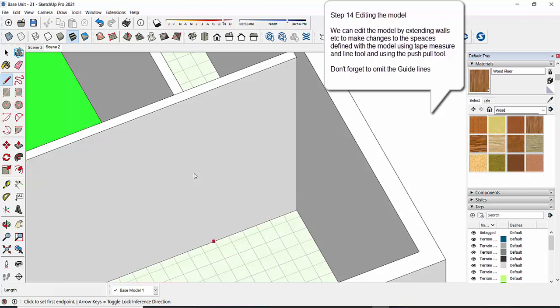So if I wanted to create an opening, it simply is to use the pencil. It needn't necessarily be rectangular. I can define the height of where the opening is going to be. So let's come in at 2.1 meters. Let me just draw a line across. So you see I have a red line.